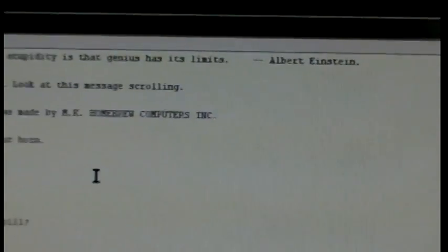So let me demonstrate first how the setup looks. Once you click setup, another dialog box opens and you have just a simple text control. You enter texts to be scrolled over the board line by line. Each text can consist of 126 characters and there can be a maximum of 50 lines of text sent to the board.